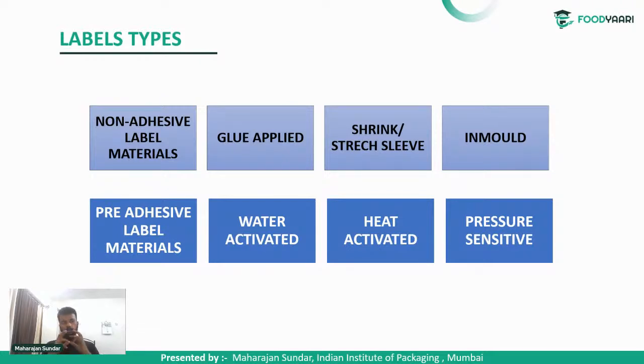In-mold labeling is a brilliant technique, but it is not used majorly due to limitations in cost. While making the bottle itself, the label material is placed inside the mold, and then the bottle is made. It is done only for rigid materials. Before the rigid material dries, the label will be fitted, during its natural drying process.